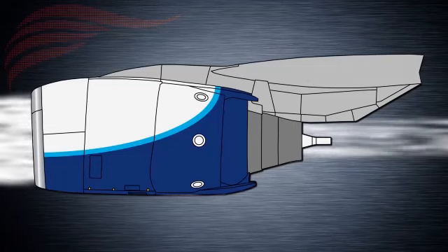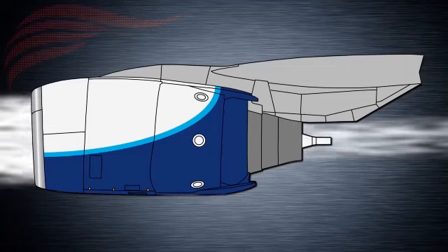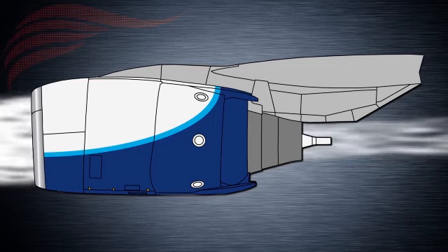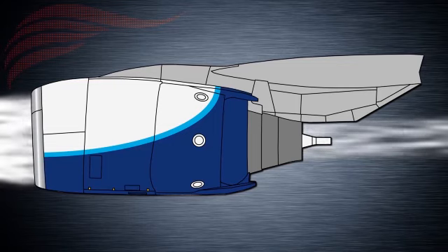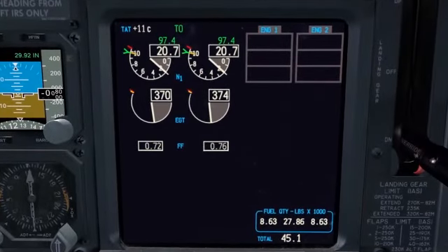A surrounding engine cowling protects all the engine components. This cowling has an aerodynamically smooth surface in order to minimize drag. Access doors are available in order to perform maintenance. In addition, in the event of a foreign object being ingested into the machine, this cowling works to contain engine components if there is a breakup. Flying engine parts don't bode well for anything on the aircraft, including passengers. To put things in simple terms, the secondary and primary bypass air work in conjunction to create thrust, or fast-moving air, that drives the aircraft forward.